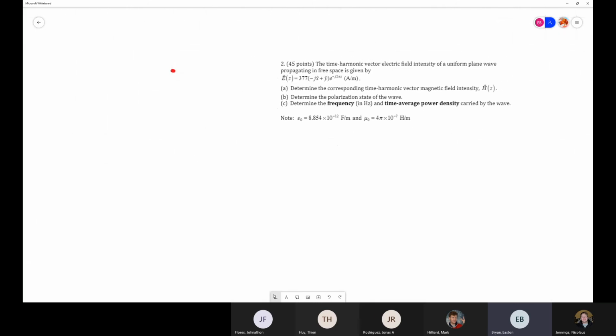The reason we go with phasors a lot is because they're easier to work with. The integral form of Faraday's law is better for finding the actual EMF or the current, specific values like that. But the differential form is really useful for giving a relationship between magnetic and electric fields. So using the differential form is a lot better in this case, since we're given one field and trying to find the other.